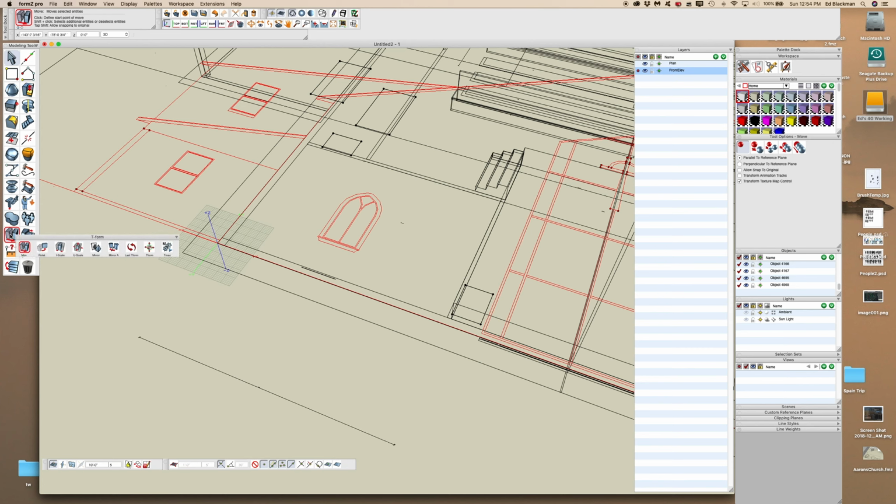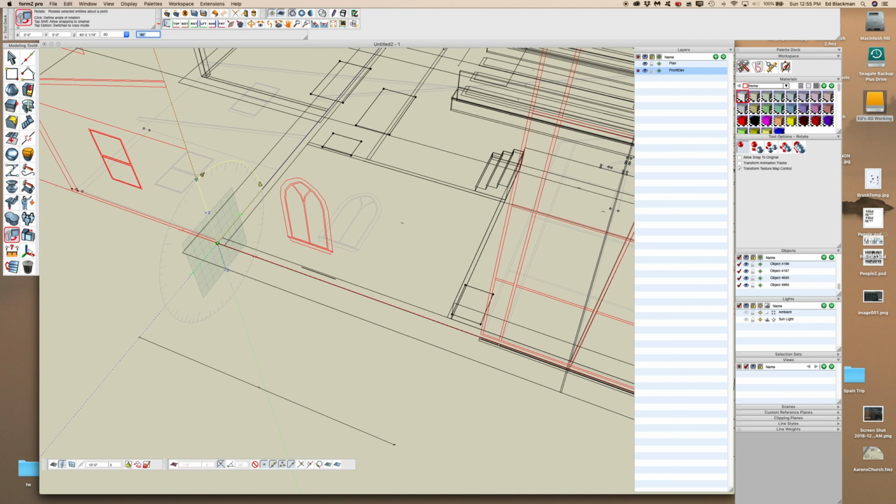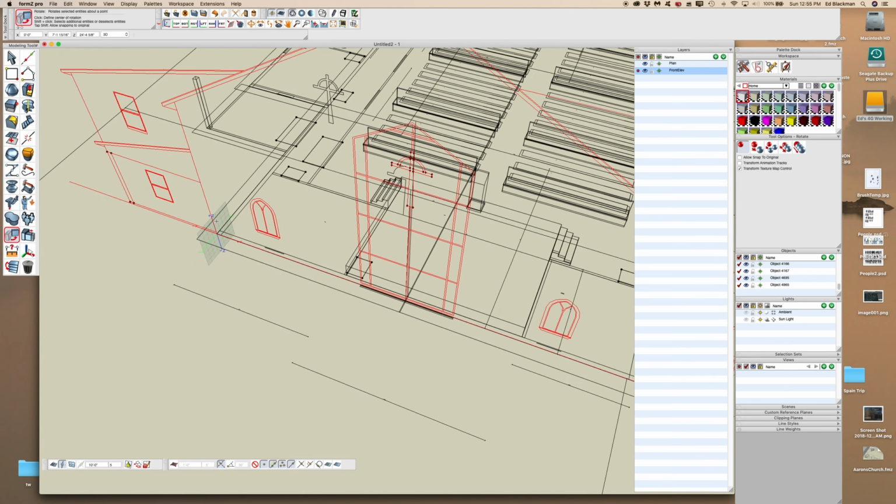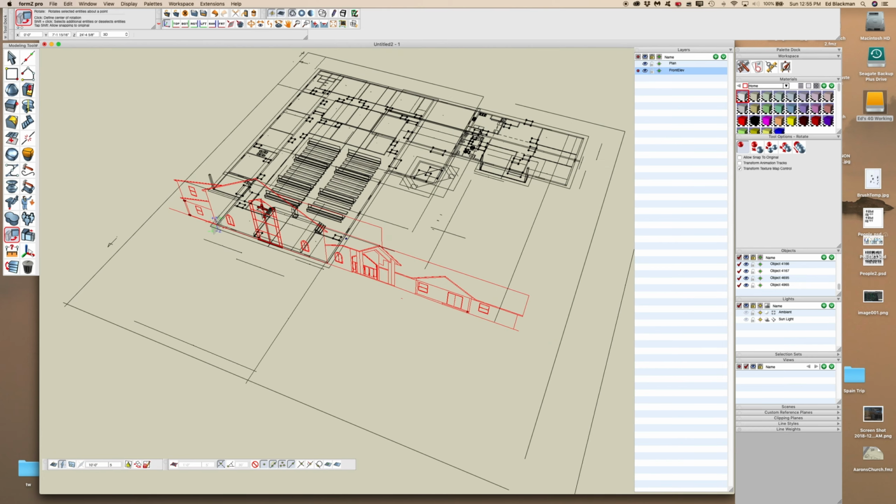And so we'll go to the move palette, go down here and go to rotate. Now we don't want to rotate it around this axis. We want to rotate it around this axis, okay? Because it's going to rotate up. So go back into that corner with the rotate tool selected over here. Go down in here and click on it and go up anywhere along that line and go up until it clicks 90 degrees, and it'll click a little green dot. Now you've flipped that elevation up in the correct orientation.